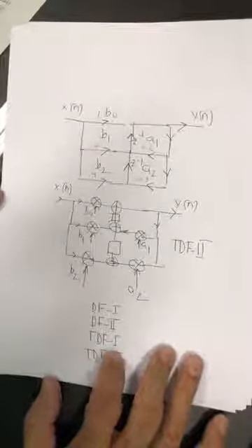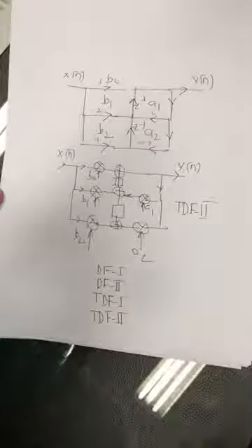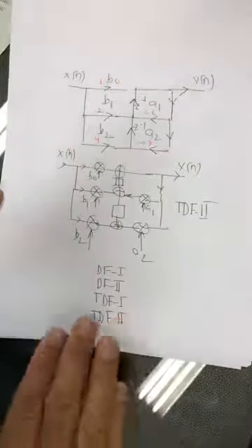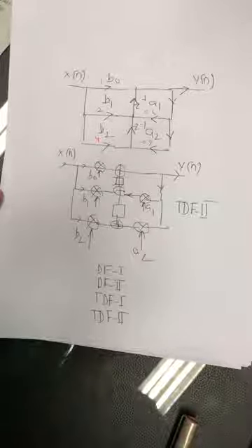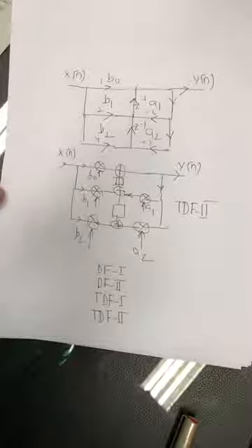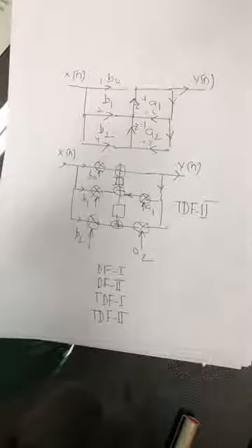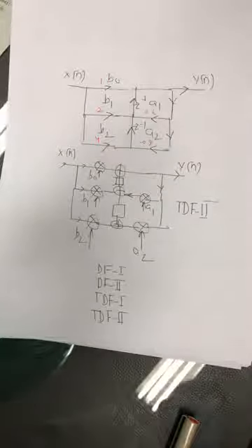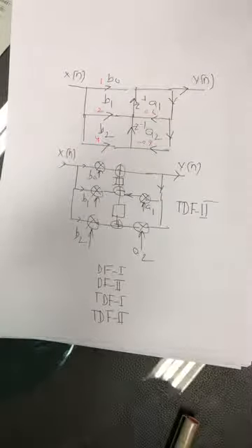Or the second method is to go through the lengthy process: convert this into direct form 1, then cut them into 2, put them here and here, direct form 2, and then change all the arrows, input to output, transpose direct form 1, and do the transpose direct form 2. So a question in the exam can be easily solved if you have an equation and the appropriate direct form. Let me run you through a few slides so that you will also find out what the benefit is.